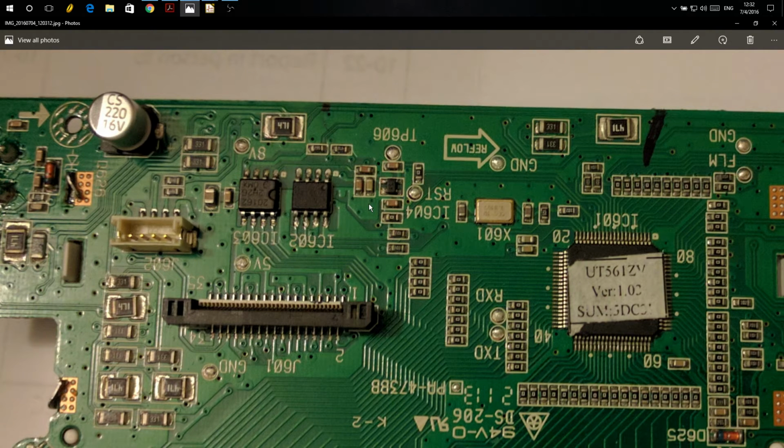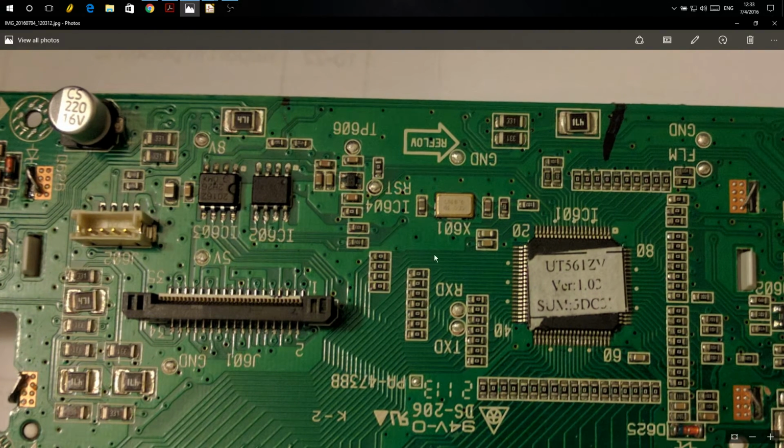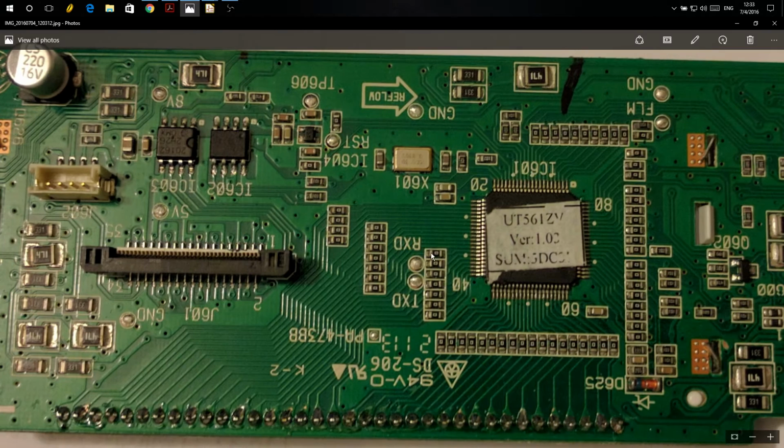So once the voltage goes below a certain threshold, it'll drag that pin back down again, so it causes the micro to reset. They're kind of handy, but it's probably because this doesn't have built-in brownout detection like an Atmel does. So they have to have an external supervisor. So if you ever have one of these radios and it just seems dead for whatever reason, one of the first things you're going to check, other than voltage, is do I have 5 volts?